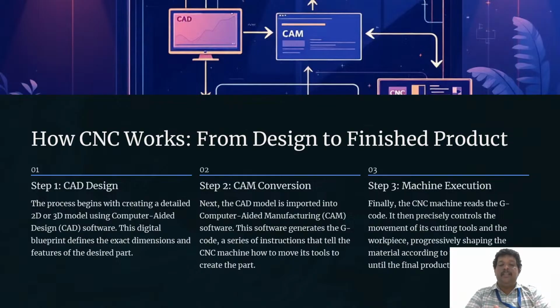CAM is computer-aided manufacturing, and for this computer-aided manufacturing you have software like SolidCam, Symmetron, MasterCam. We have many other options. So what will these softwares do? Once we make the program, they will convert it into G codes and M codes. This G code and M code, as I told earlier, will be the instruction set given to the system. The computer will accept this, and then it will process as per the instructions given to the CNC.